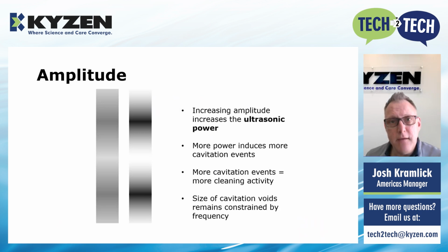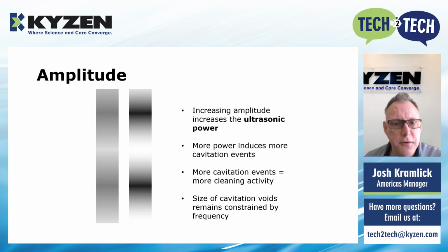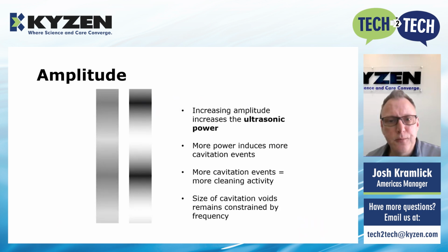Those greater number of cavitation events equate to a higher cleaning activity in the bath, but the size of the cavitation voids remains really constrained in general by the frequency that you're operating at. So what you'll see here, again, both same frequency, but with the higher amplitude on the right, we're getting a higher number of cavitation events per cycle.